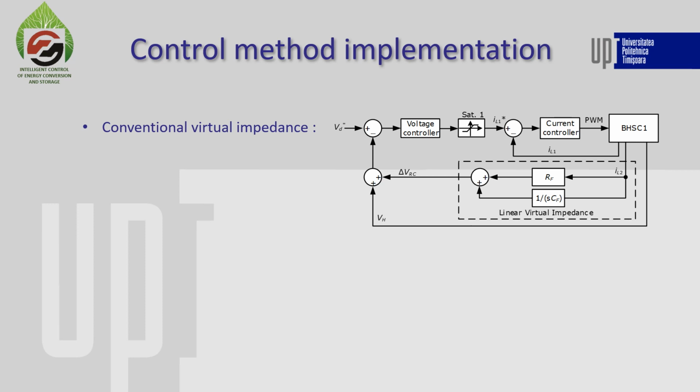Here the voltage on the virtual filter resistor RF and the virtual capacitor CF are added because they are connected in series. The resistor voltage drop is calculated simply by multiplying the current and the resistor value, and the capacitor voltage drop is calculated by integrating the output current.